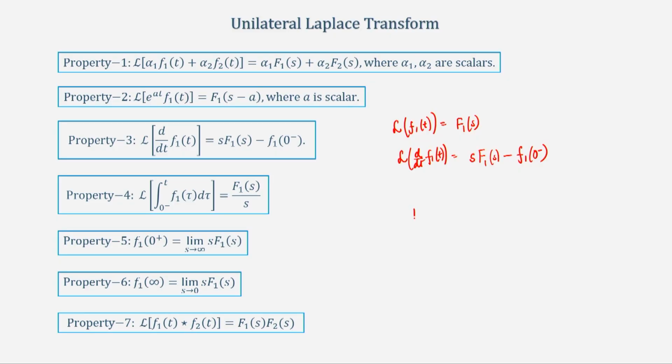So, basically, suppose there is F(s), and this is the Laplace transform of f(t) actually. This is what it is. So, if I say sF(s), you should think, oh, s multiplied by F(s), that means the actual signal must be the derivative of f(t), with the assumption that f(0) is equal to 0. That is what it is. This will be very important for us, because this will be required when we talk about controllers and all.